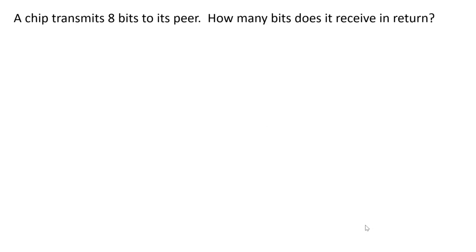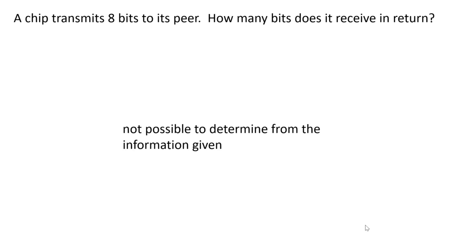Chip transmits 8 bits to its peer. How many bits does it receive in return? Well, there's no way to know. It depends on the protocol. Some protocols like SPI will send 8 bits back. Other ones like I2C might if you're doing a read.